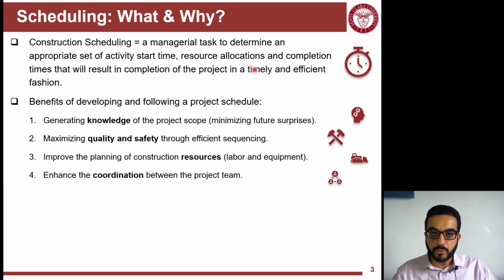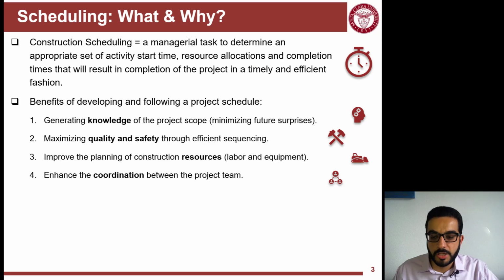And also it's good to coordinate in general between the team members. The first thing that the owner asks for in contracts when they have a contract with a contractor is: show me your schedule. I need to know that it's feasible that you will deliver the project in the time you committed to. And also the GC communicates the schedule information with the subs to let them know that you are needed on the site in this week or these number of weeks for this project.